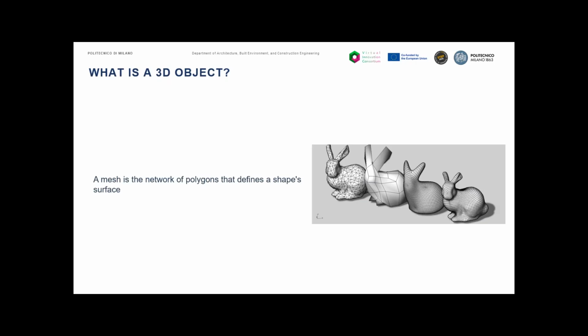Triangles actually don't have this property. So when you see a smooth movement in a video game, that mesh was built by the artist as a quad dominant mesh. Then it will be triangulated by the GPU, but that is a later process. The practical consequence is: use quad topology when modeling characters or anything that will be animated, and use triangulated geometry for real-time deployment. As said, the GPU processes mainly triangles.